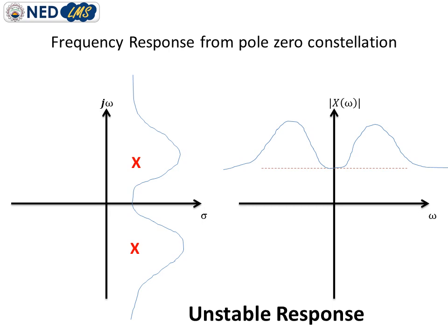So for your practice, you can sketch more and more poles and zeros on the S-plane and try to determine the stability and frequency response of that system. And if you need any of my support, you are free to ask through email or using the facility of live session.